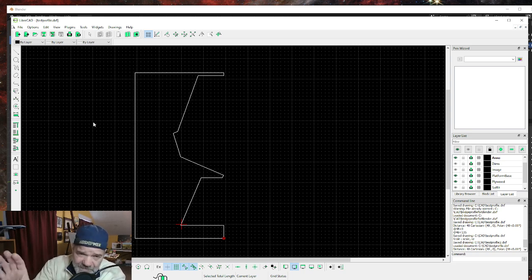But if you want to use LibreCAD, when you save this, it saves as a DXF automatically, you don't have to export it. It always saves it as DXF. Whatever units or measurements you're using in the CAD, they get interpreted in Blender as metric.